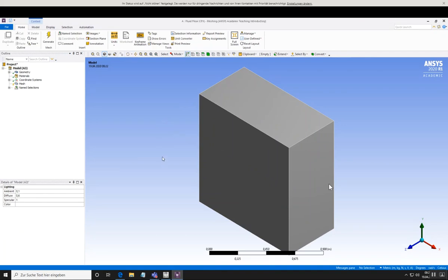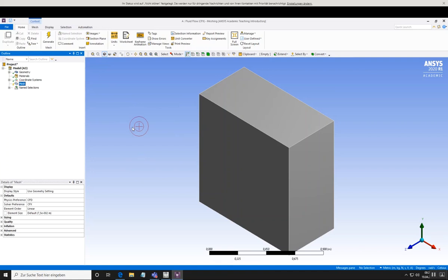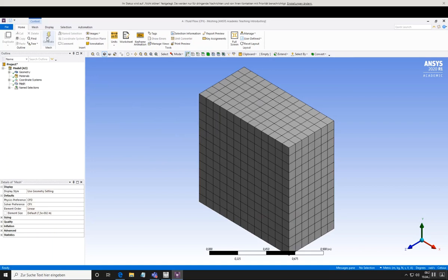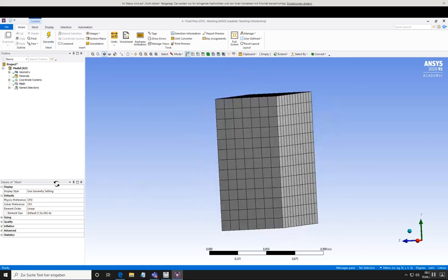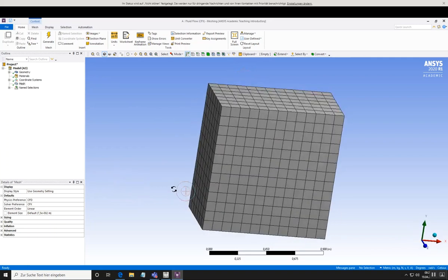Okay, takes a bit of time, don't be too fast. Let the program open everything. Look, go to mesh, nothing is generated, so I press a small button with a flash to generate my first mesh. Okay, looks pretty good. I think this is my first mesh.